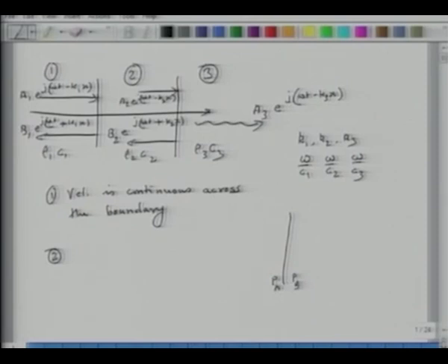If the film is extremely thin, vanishingly thin, the mass of it is 0. But if you have across a film of 0 thickness a non-zero pressure difference, then that means it will have infinite acceleration. But in reality that doesn't happen. So pressure is continuous.